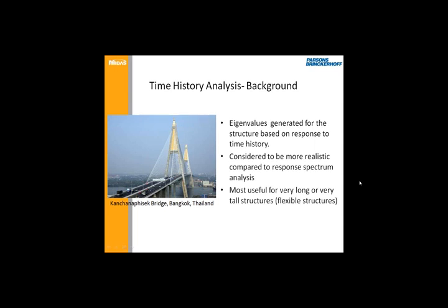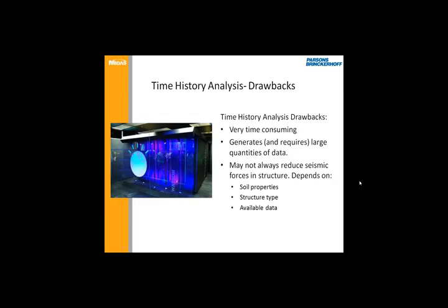Okay, so time history analysis is similar to response spectrum analysis in that eigenvalues are generated on the structure based on a response to the time history. This is considered to be more realistic compared to response spectrum analysis, and it's most useful for very long or very tall structures, more or less flexible structures.